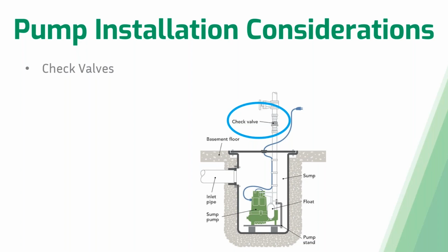water in that pipeline. If you don't have that, the water is going to all come back into your sump pit and will thus cause your pump to do more work than necessary. So a check valve is always going to be recommended.